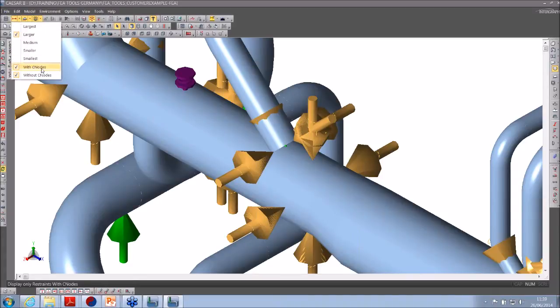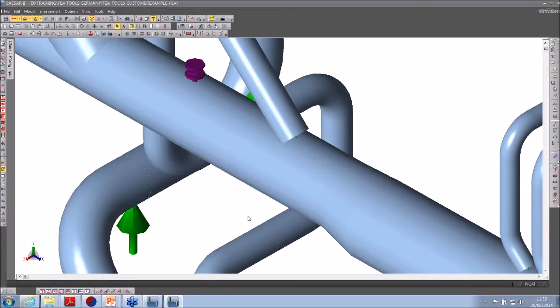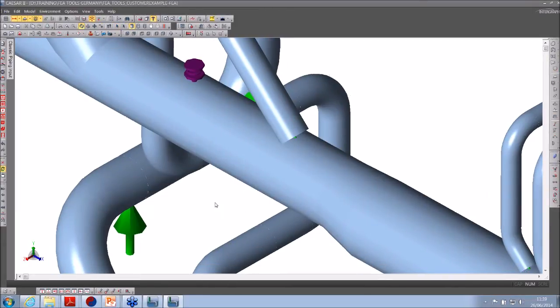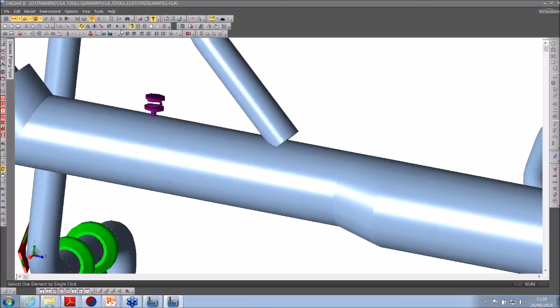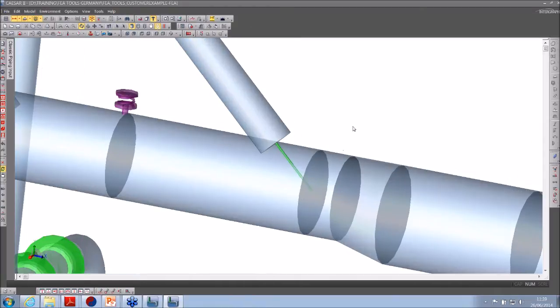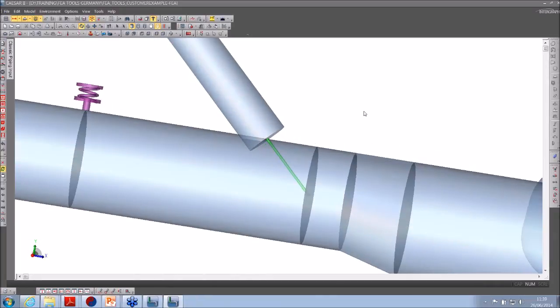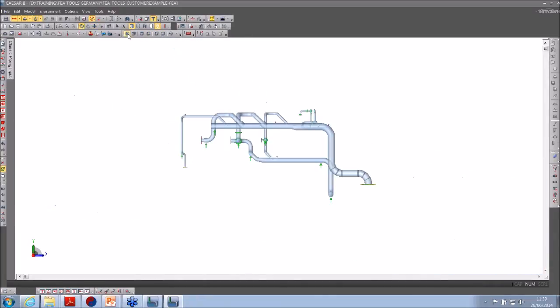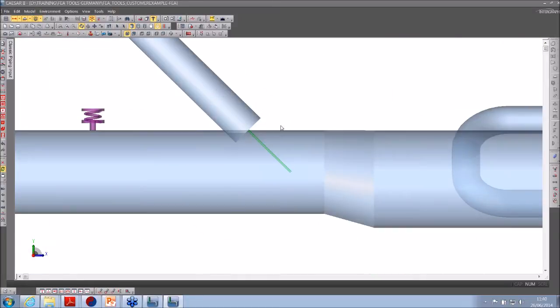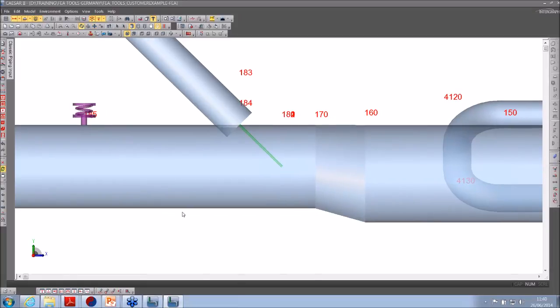and I've got a much more accurate model. Now what I'm going to do is I'm just going to turn off this and hide all the restraints with C nodes, just so I can see a little bit better what's actually going on. And let me go to translucent mode, and this is what I was going to show. If I go to the side view, it's just to see how the model has changed. So if I can put node numbers on it, yep, it's not crowding it too much.